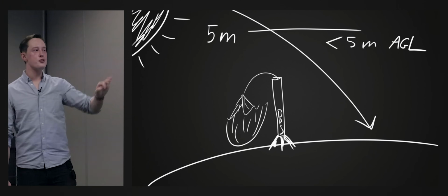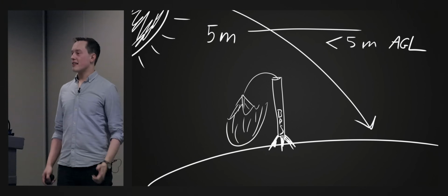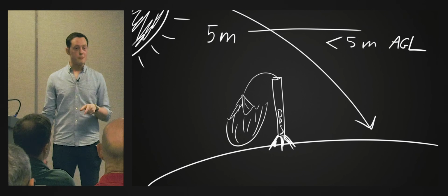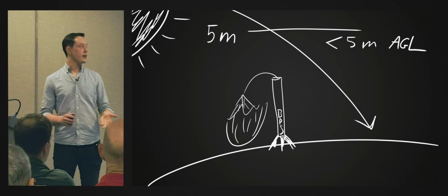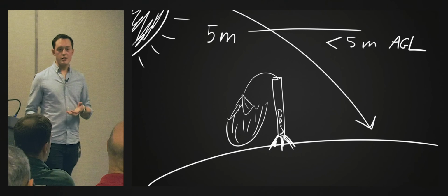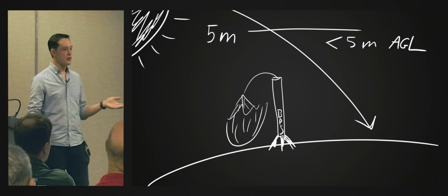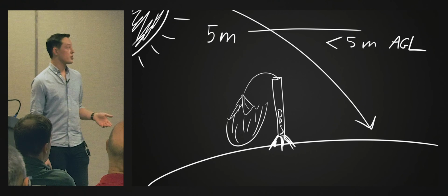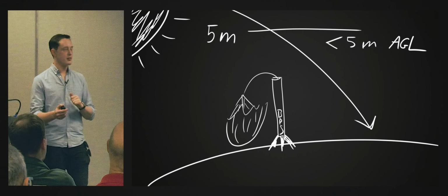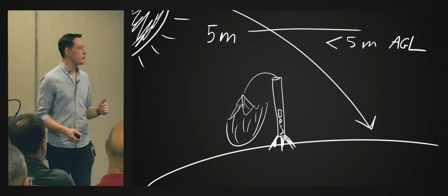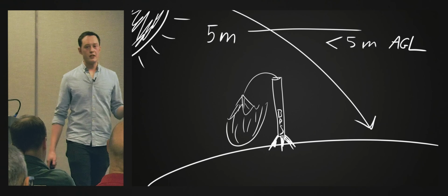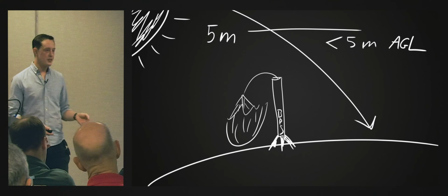we can detect that we've landed. Now, after drawing this, I thought about it harder, and I was like, wow, there are like 1,000 ways you could detect landing. Technically speaking, you could detect it by looking only at the gyroscopes. You could see if there's just no movement at all. When you're under parachutes, you're always going to be rolling or moving in some way. And so you could look at the gyroscopes to see what the standard deviation is on those over a period of 10 seconds. You could look at the altitude as well. You could look at the accelerometers to see if one axis or two combined axes show 9.8 meters per second squared to sense gravity. Although that's a lot harder because when you're under chutes, the acceleration is going to be very close to that. Anyway, the point is that there are lots of ways to detect these types of things.